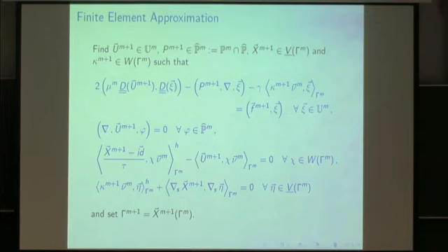I got a question about the normal before. Here the normal is the true normal on your discretization. So that will be a piecewise constant discontinuous quantity. Again, what was the capital V, the finite element space for the displacement? That's just piecewise linears with 2 components in 2D and 3 components in 3D, so it's vector valued. Then the velocity is P2, and you use it to move the interface, which is P1. Is that correct? Yeah. Then you lose something.